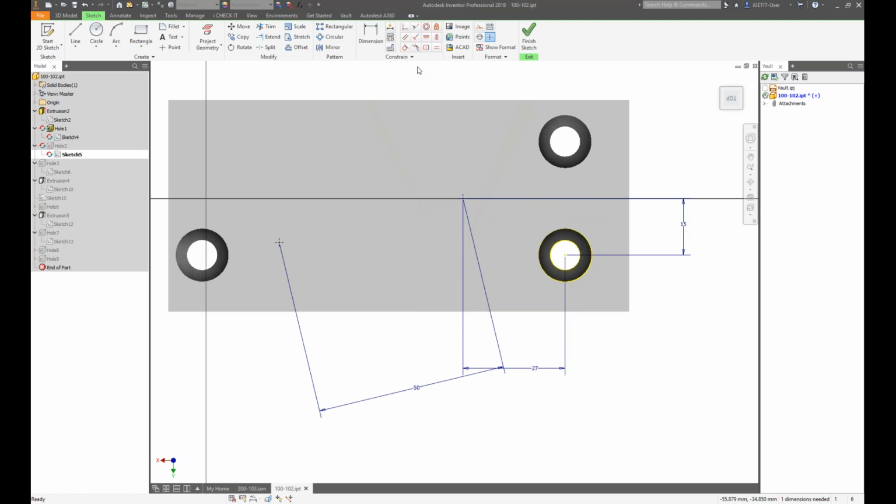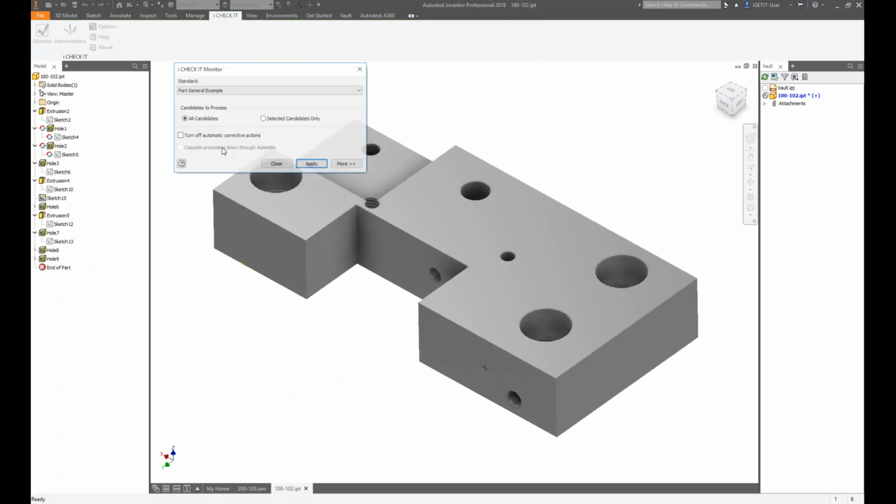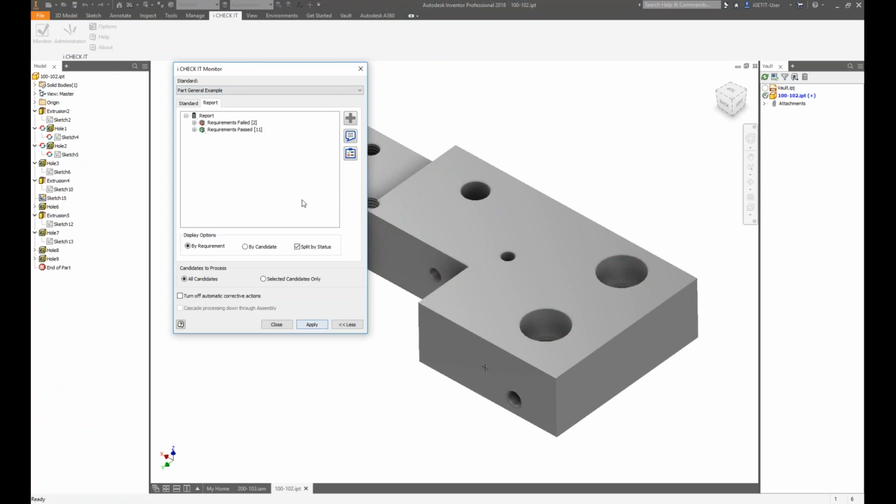So in that case, this pointed out to us without having to do much work at all that there was already an issue in this particular sketch, where we would have maybe never found it later. Then something accidentally gets changed on this part file, and that center point gets moved, and now you've got a design issue with your part later on down the stream, and you didn't even realize that could be a potential problem. I think I got 2 more.